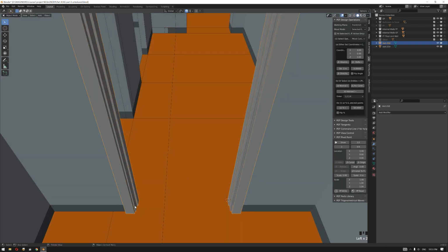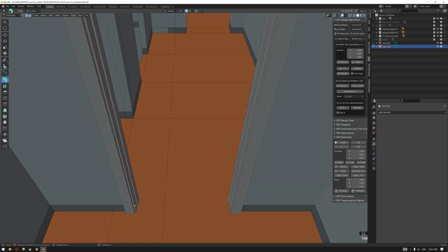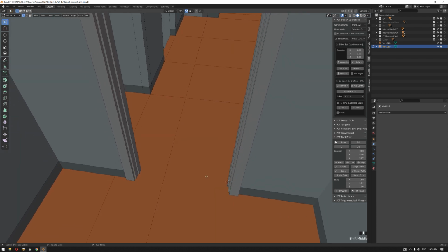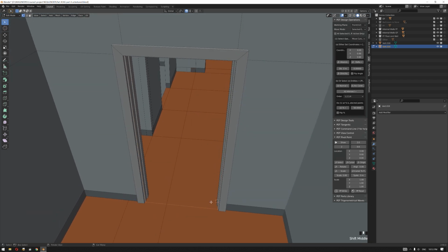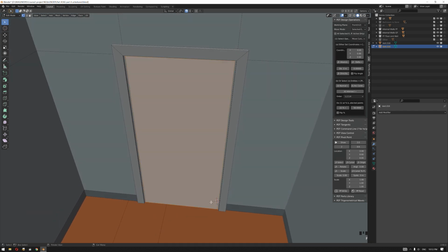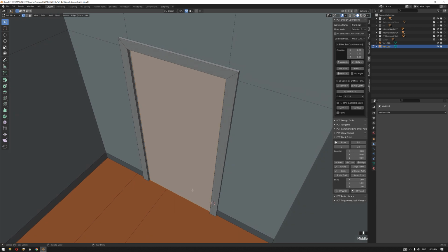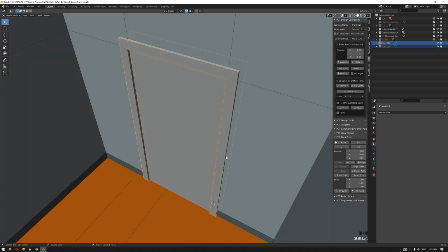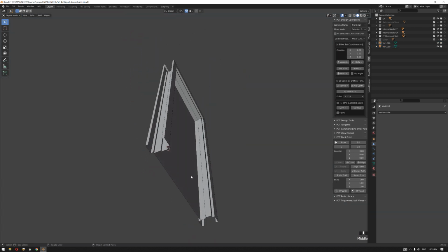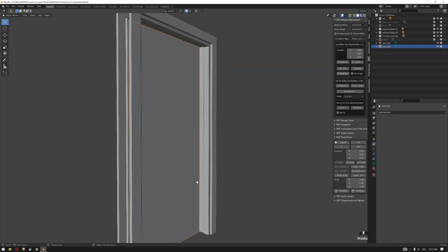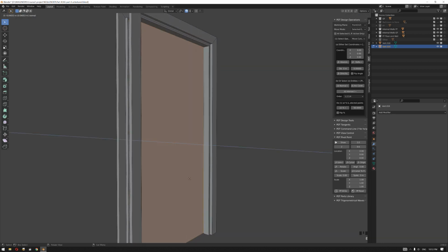And let's select this shape, press Tab to enter into edit mode, 1 for vertex, W to select my rectangular, F to close the shape, A to select all the vertex, F to extrude that shape. Now, let's isolate these guys together, and let's extrude our door by this value,